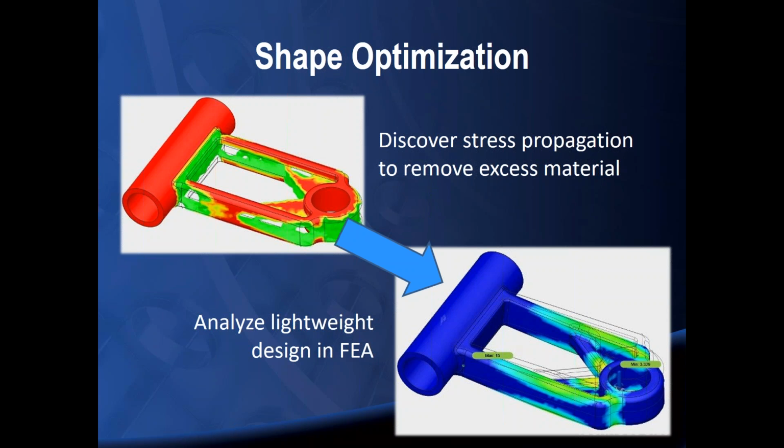And so those different types of simulations are all wrapped into Fusion 360. Some of them are inside of the Fusion 360 Ultimate version. The linear stress analysis and the thermal analysis are all built into the standard Fusion 360. The shape optimization, the dynamic analyses, and the event simulations are all part of the Fusion 360 Ultimate version. And so depending on which version you have, that'll determine which simulation types you can run.